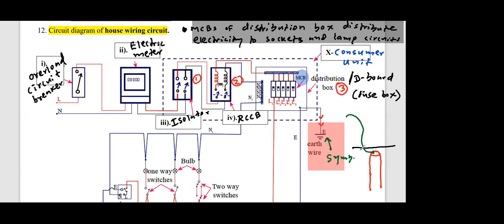Right. But sometimes in coastal areas, this underground metal pipe can get corroded, and with the corrosion this green cable or wire can get disconnected. Then when there's a leakage, even though the trip is working, there's a problem. Therefore, earthing is for your safety, for the safety of the consumers and the electrical appliances. Right. So let's move down.